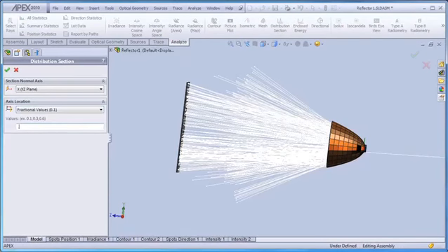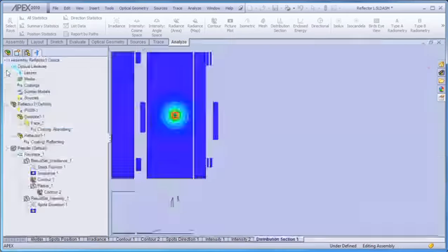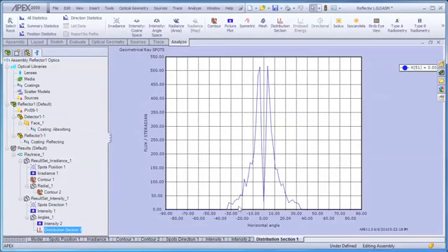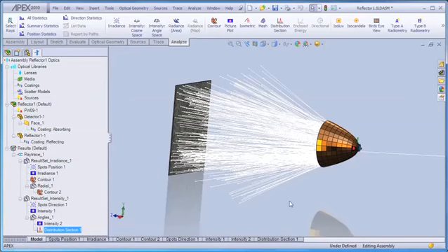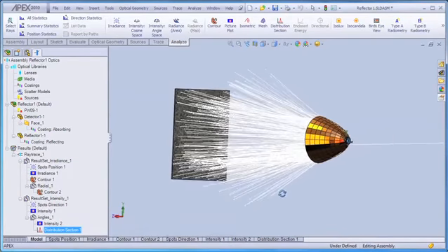And we'll create that far field view at the halfway point of our intensity plot. And we can see again in the cross-sectional view the central hole in the far field intensity. And we can see that the total angular distribution of our system is approximately plus or minus 35 degrees. Now, these are just a few of the types of analyses that can be performed in the fourth and final step of the Apex workflow.